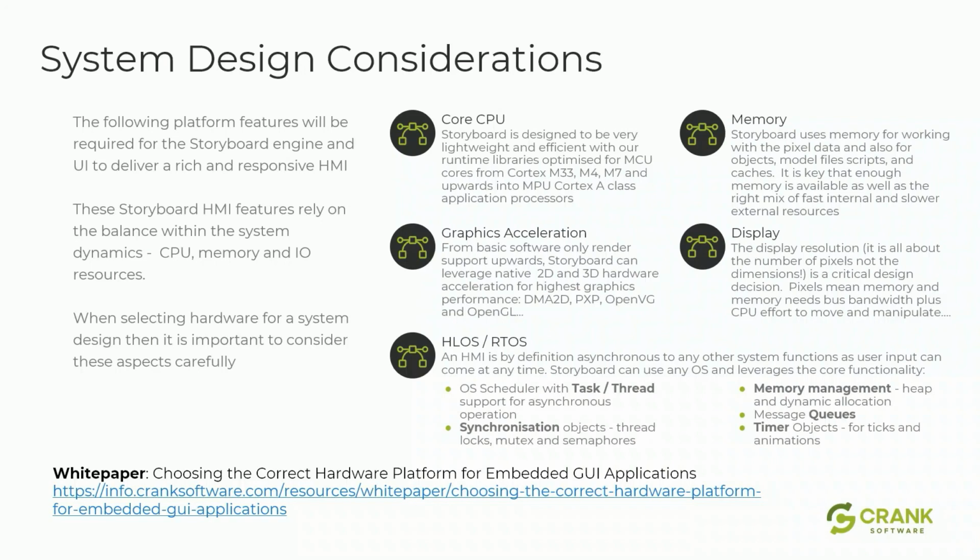And in terms of the operating system, Storyboard can run on anything, really. We often get asked about bare metal. So really, fundamentally an HMI is asynchronous. So you really need the concept of a task, a scheduler, to be able to manage the front-facing UI tasks with background operational tasks, spinning motors, blinking LEDs or whatever else your application does. So you need a task construct. Along with that is synchronization to manage those tasks, so semaphores and mutexes and thread locks and such.